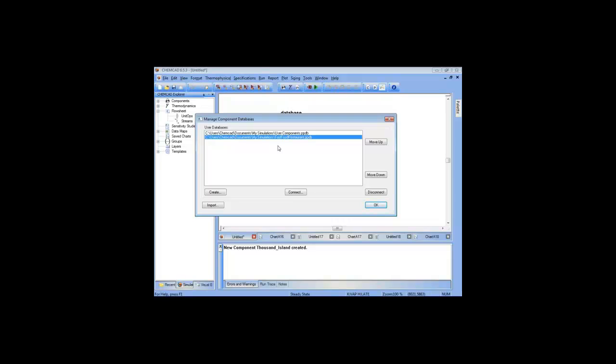Elect an official database manager who is the person responsible for changing the values in the official database on the network. I would also suggest if you have different projects for different customers, consider making a different database for the official version of the project for that different customer. If you're a consulting group, this is an easy way to separate confidential data for that customer. The database does not need to be in your documents folder. You could put it in a folder which is clearly named confidential.